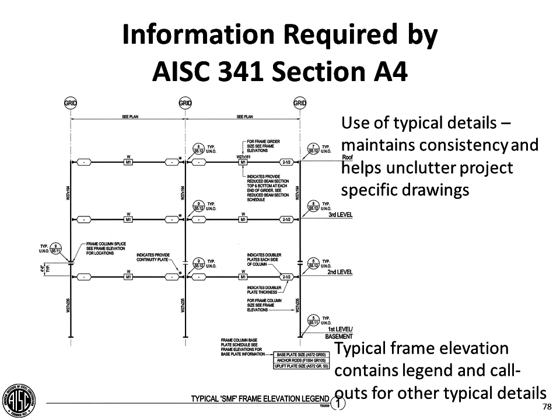What many engineers also do on their typical details for seismic systems is to try to produce typical details for the basic system that they're looking at, in this case a moment frame. Now the actual moment frame may be more than the 3 stories that are shown here, but this detail shows the basic requirements, and again allows you to show that information in a consistent way from project to project. It also allows you to use the frame elevations to talk about the specifics related to the project that you're working on at that point in time.